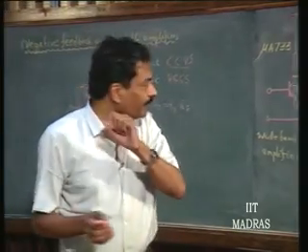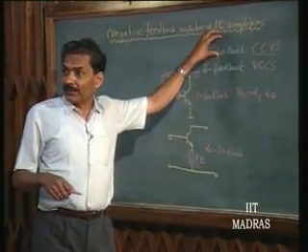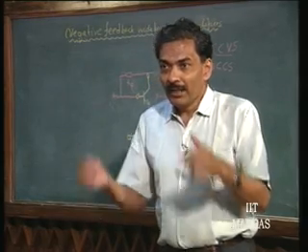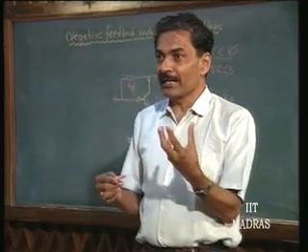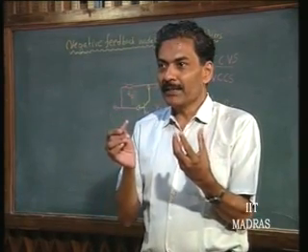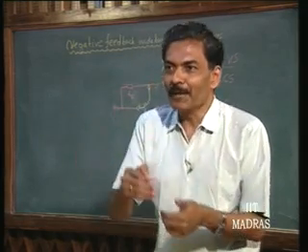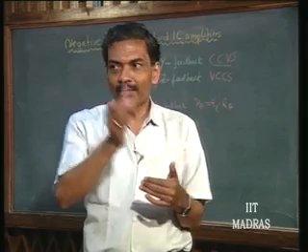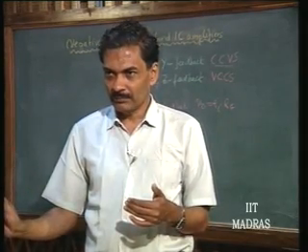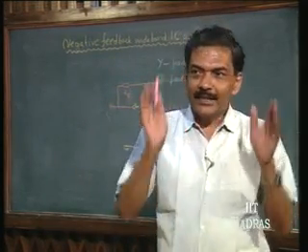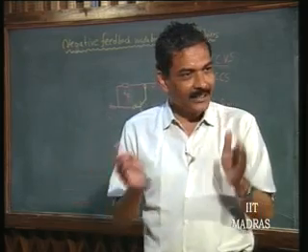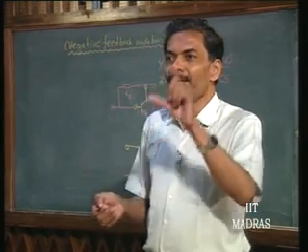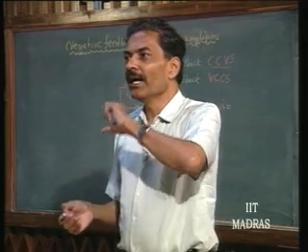That all depends upon your proper identification of the feedback, and what it is that gets modified. When you give Y feedback, it is the Z matrix that gets modified automatically. All the Y parameters will simply add, and it is the Z parameter that will get modified. Those Y parameters will be divided by delta Y, which will involve the loop gain. Therefore, all the Z parameters like Z11, Z12 and Z22 will go towards 0, and Z21 will go towards the stabilized, desensitized value. And how is it getting desensitized? Because of the loop gain coming into the picture, and the desensitized value is primarily going to depend upon the feedback component. It is not going to depend upon the active device.